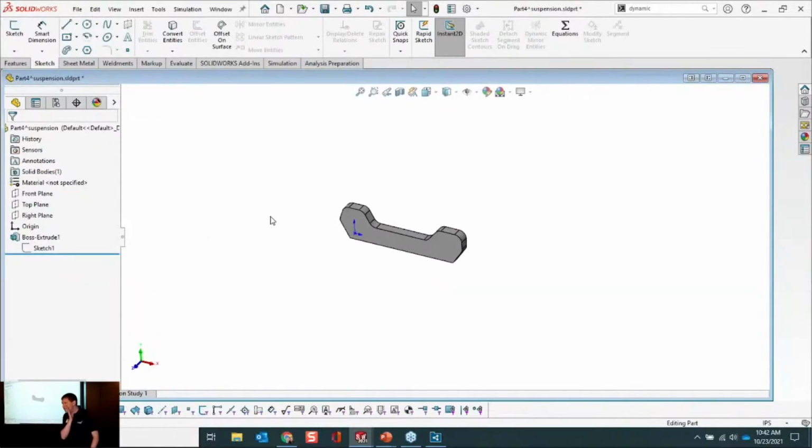Now, of course, when I go back to that assembly, it's going to be shifted, right, because I moved it from the origin. Well, now that those references are gone, I can just mate the part as it's supposed to be to begin with, and then I can continue along my way. So this workflow for creating externally referenced parts, like if you're just trying to trace a part off of something that already exists, but you're afraid of external references, you can still use external references, just use this trick, and then you can back out of it and make an actual part that you can engineer.